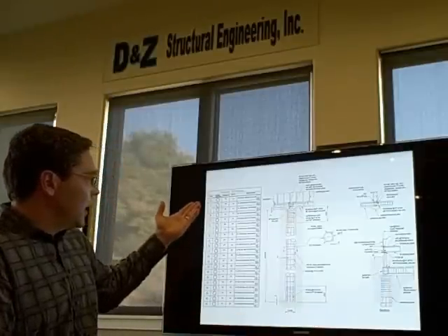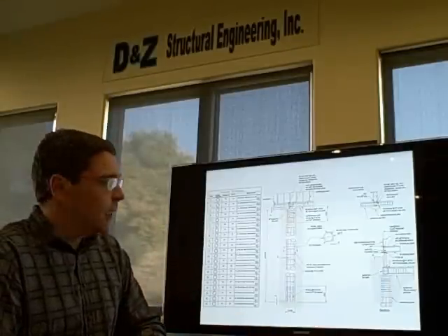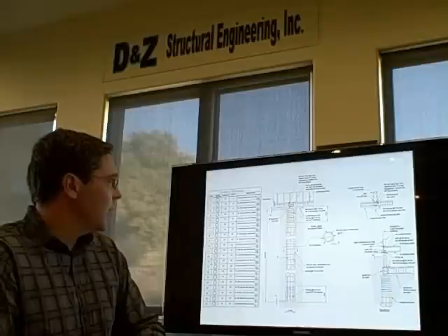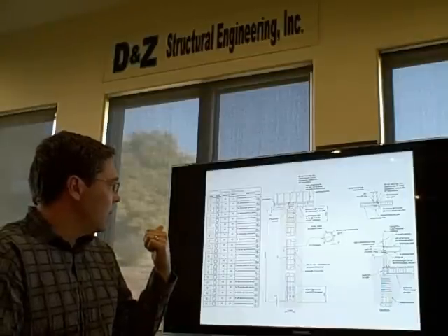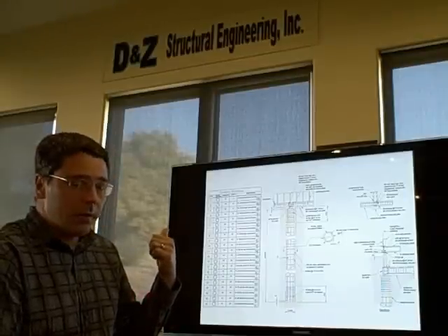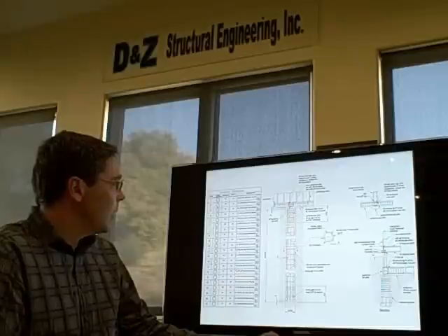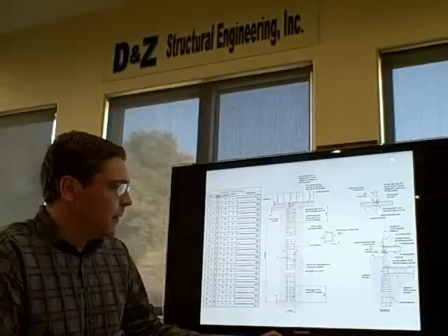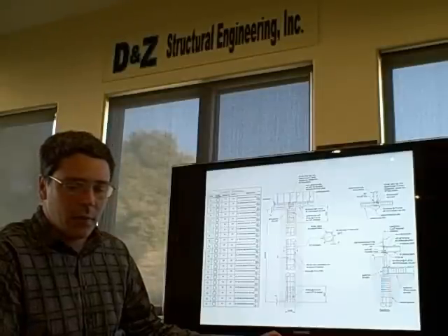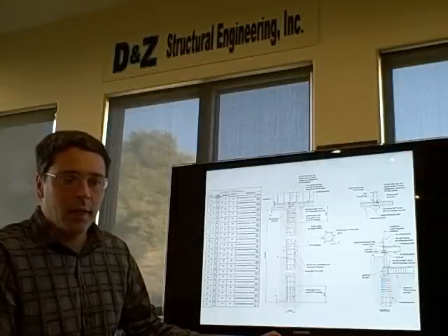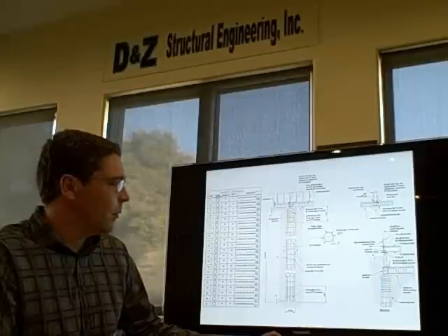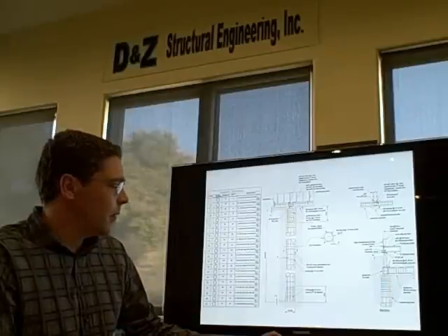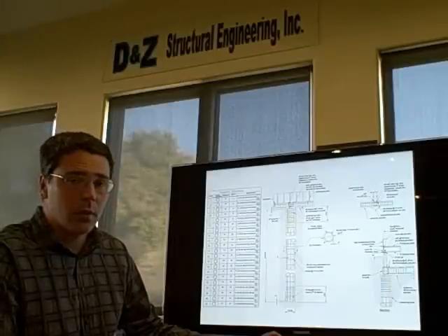We'll come up with a caisson schedule for our projects that will identify to the contractor exactly the diameter of each caisson and the depth required, and also the steel required in the caisson. We do this in a fashion to not have the same exact design everywhere in order to get economy. So some of the designs can end up being a little bit less expensive because the loads are a little less.